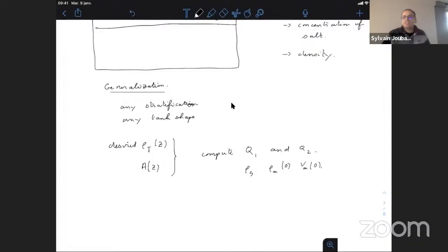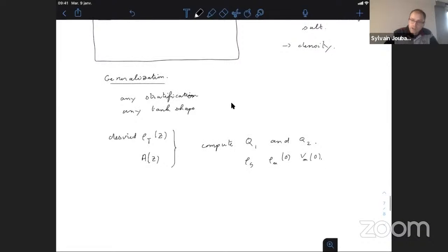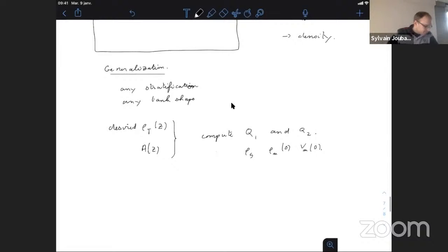And you also have a limitation of the pump for the flow rate you can have in the lab, and Q2 has to be small. So getting all these limitations, you have some solutions to this problem, and you choose the one which is the best for you. And you can have the stratification you want by this generalization of the equation I've shown you before.